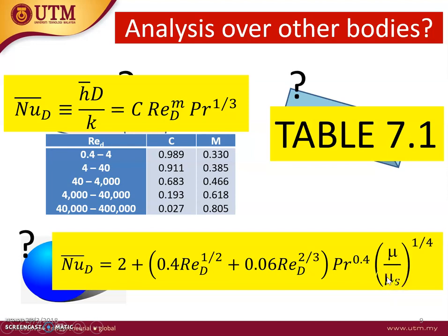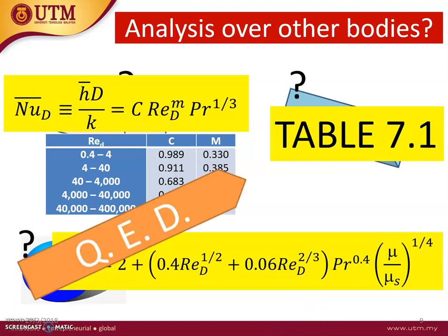Yes. So, for most of these correlations, they are applicable for engineering calculations in practice, but they are not exact. The error can be as large as 25%. So, make sure you understand fully under what conditions these correlations are applicable.